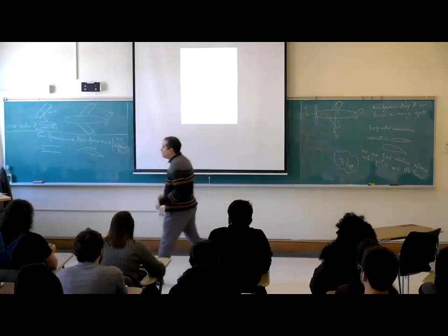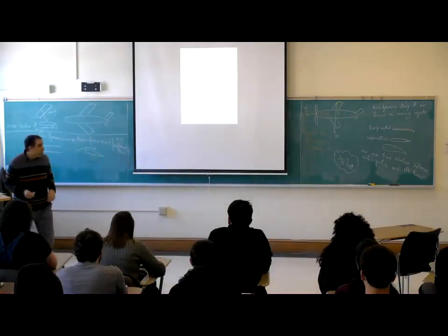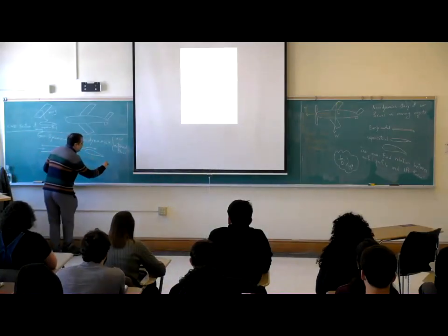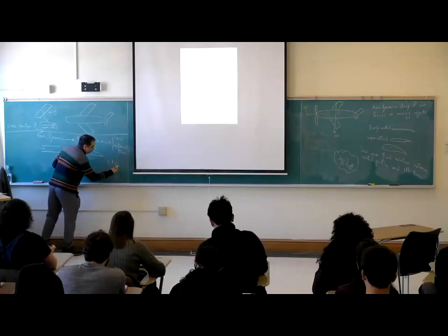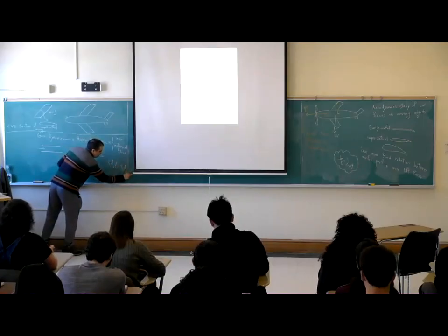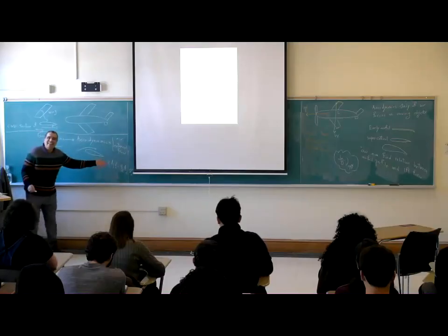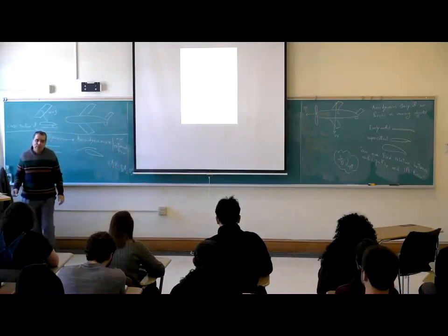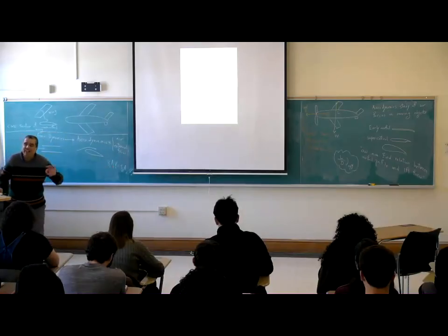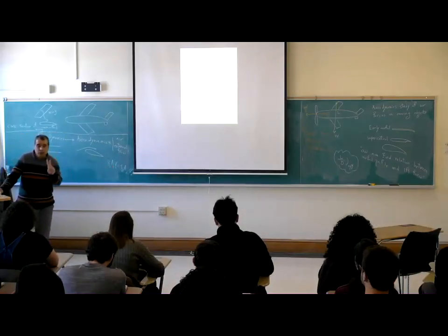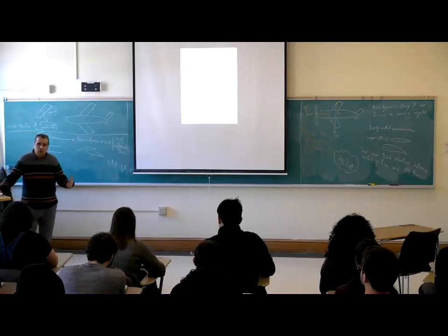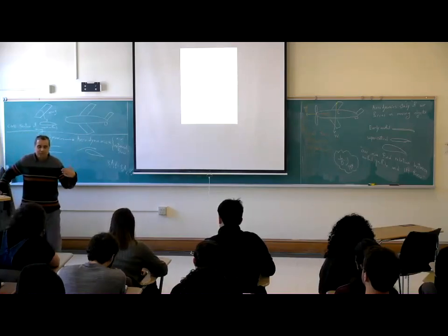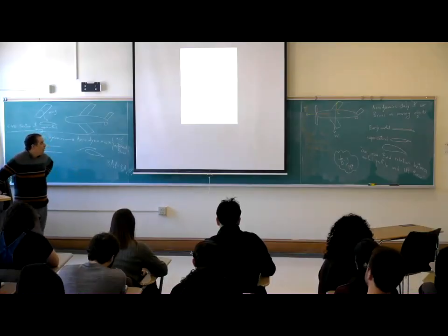Okay? So for example, in fluid mechanics, you write continuity as rho 1 A1 V1 equals rho 2 A2 V2. This is the integrated form of the continuity equation. There are two other forms: differential form and integral form. I will derive both of these equations for you.